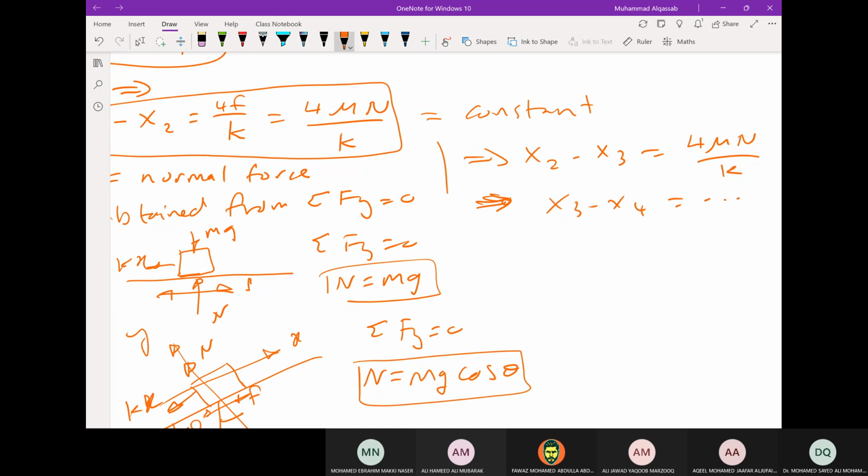As a comparison, with viscous damping the frequency depends on zeta, which can be either omega d equal to omega n square root of 1 minus zeta squared for zeta less than 1, or equal to 0 for the others. And for the underdamped case, the ratio of amplitudes is constant. Here the difference is constant. So those are the characteristics.